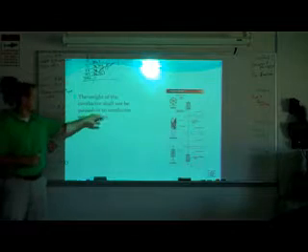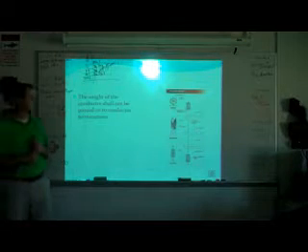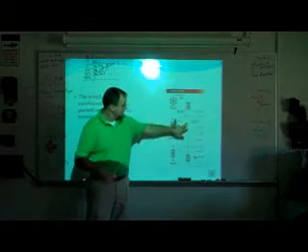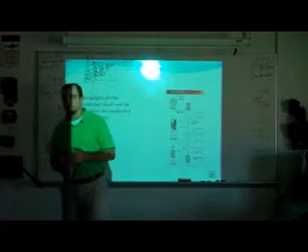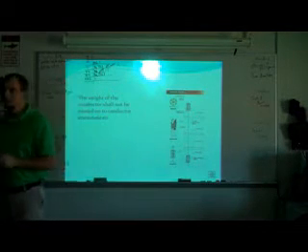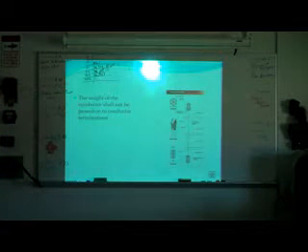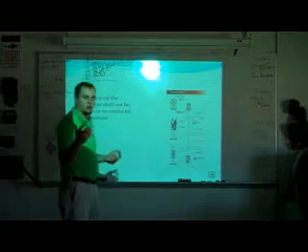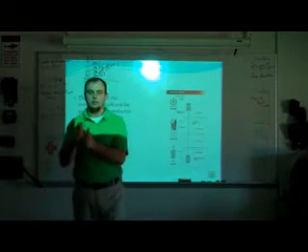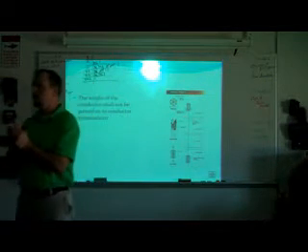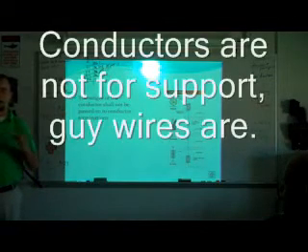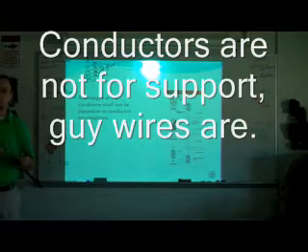The weight of the conductor shall not be passed on to conductor terminations. So what they're saying here is don't hang stuff by the conductors. I mean, that should be common knowledge. Even when you have a control push button for a hoist, you don't use the conductors to hold it up. You run a guy wire, a support cable, with it.